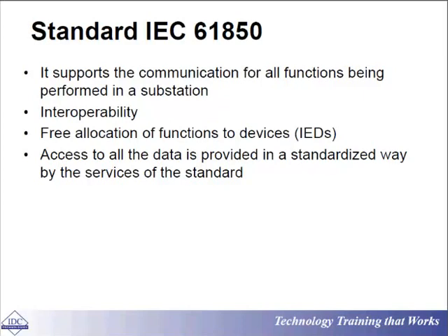It will look at everything like a function. It doesn't matter whether it is control or protection or SCADA or what. It is looked at like a function. So what is the purpose? The purpose is interoperability, and free allocation of functions to devices, to IEDs. I would like to allocate this task to this. This is a protection relay, yes, but at the same time it's an IED. It does the metering, the measuring, the control, the protection, the communication, many different things. I would like to call it the IED.